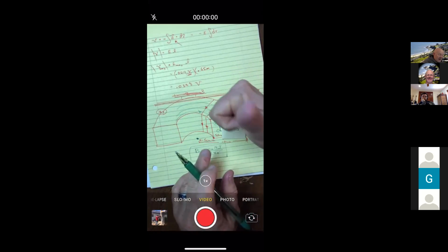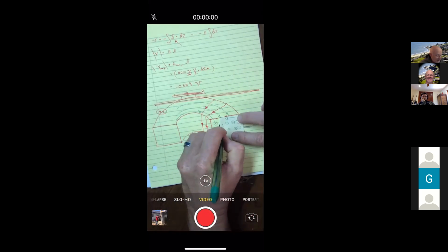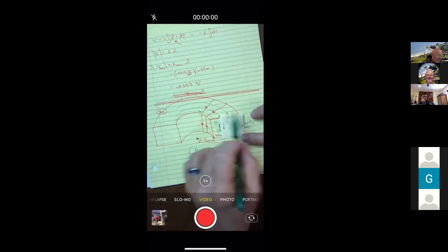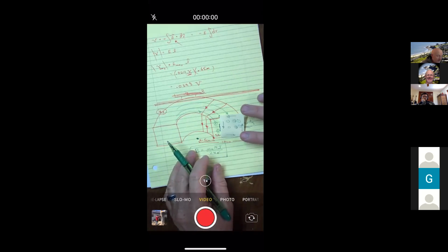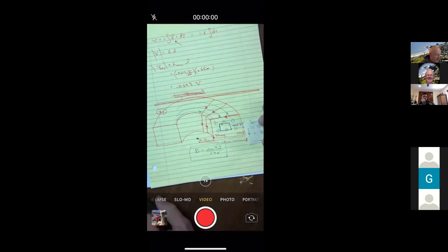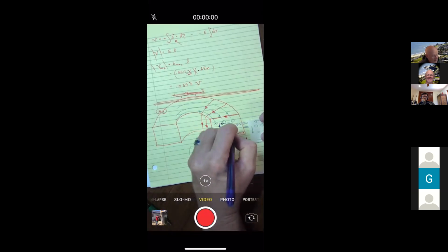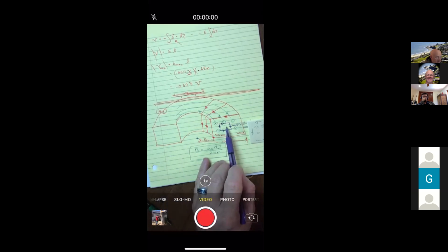So if I take my right hand and point my thumb out, the current then would be flowing in a direction that would be counterclockwise. And so the current would be in this diagram, if I, whoops, I should do that in purple, should be flowing in a counterclockwise direction so that it makes flux coming out.